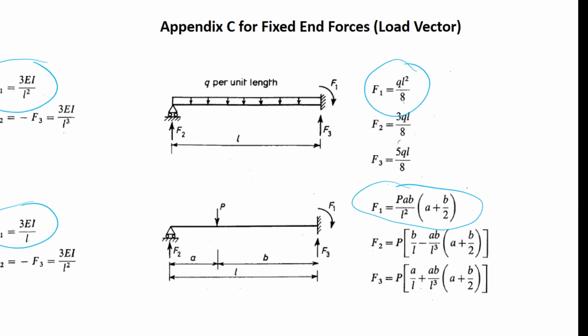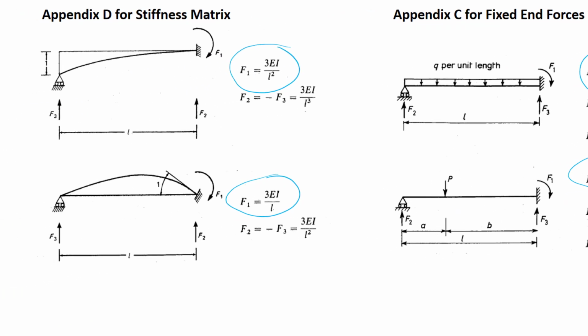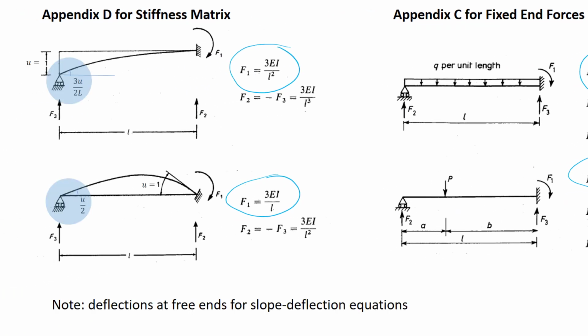The last modification has to do with method 2 of force recovery. For method 2 of force recovery, we need to know the displacements and rotations at each end of the member. So as we solve the process, we will find a certain value of u that might represent the displacement relative between the 2 points or the rotation of the node that connects to the rest of the structure. And this second one is going to be much more common in continuous beams.